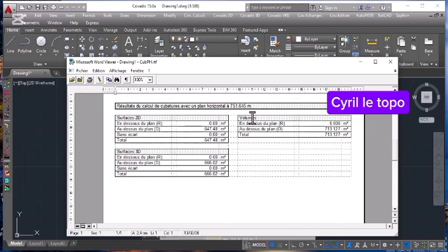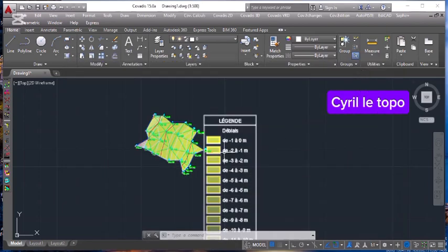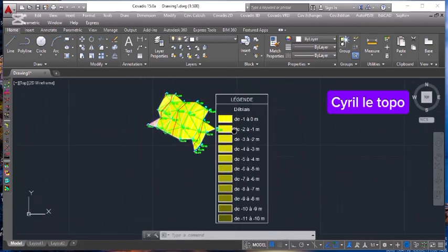We have here the volume. We can see below the plane we have nothing because our road was the lowest point, so we have no volume below the plane. Then above the plane, this is our volume. These are our surface areas, then our volume. There are other methods of calculating surface area, so the most important was the volume. So that was it for our quantity estimate.